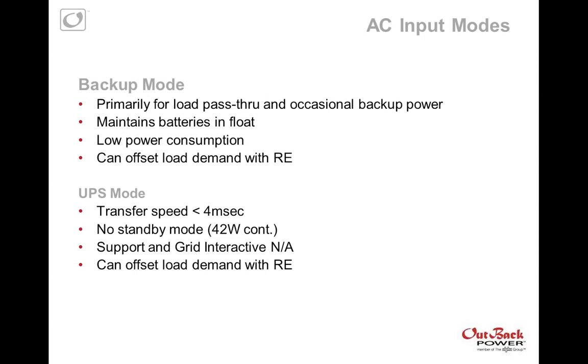So the question was, normally the batteries are only in use when grid power is not available. Up until that point, are they in float mode constantly? Yes, the batteries are in a float mode, and it will not offset from the DC side until it hits cell voltage. In other words, once you've pushed the batteries up to a high enough level, it knows that there must be some renewable energy out there that's usable. So it's okay, let's use this renewable energy. The batteries are floating because they have to be if we're up at that voltage level and there's renewable energy, hey, let's use it. I don't know if that answered the question or not. If not, we can catch that at the end if we need additional clarification.